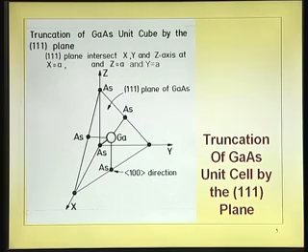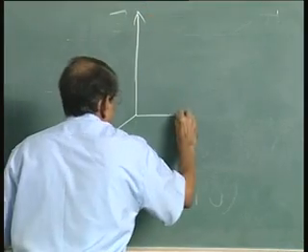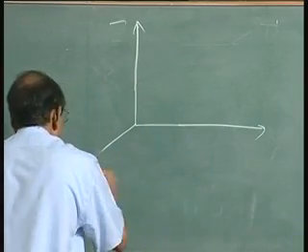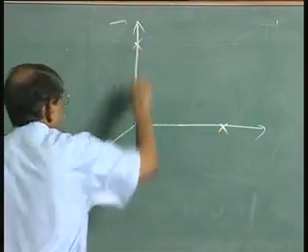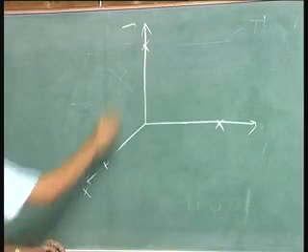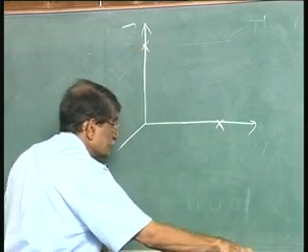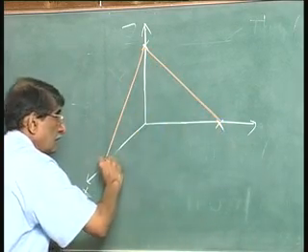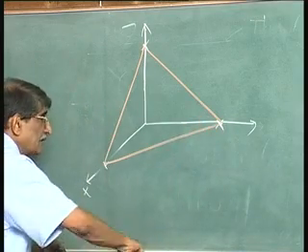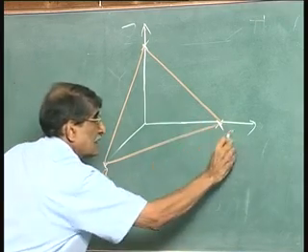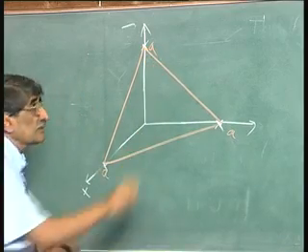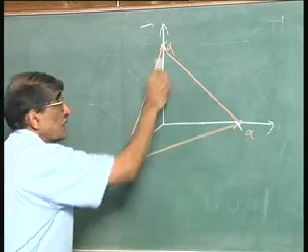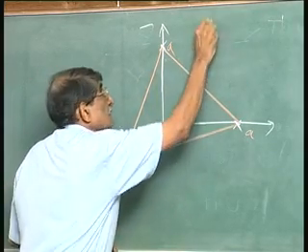So, what we are trying to see now in that picture is the plane which intersects here, here and here. Okay. That is this plane. We have marked it there. That is A and A. So, this plane intersects at 1 1 1, and the inverse of that is also 1. So, that is the 1 1 1 plane.